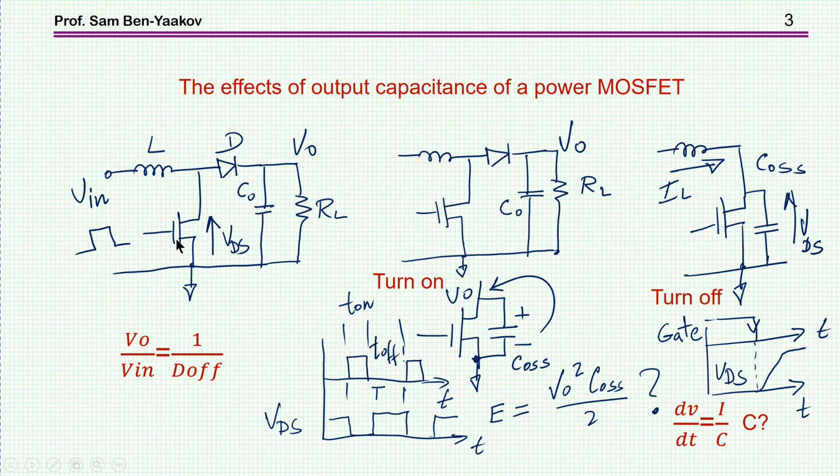When the transistor is on, that is, when there is a short or just a residual RDS on resistance between drain and source, current is flowing into the inductor and energy is charged in. Then during the off time, when this transistor is off, there is no connection here, like an open circuit, and this current is flowing through the diode to the output.